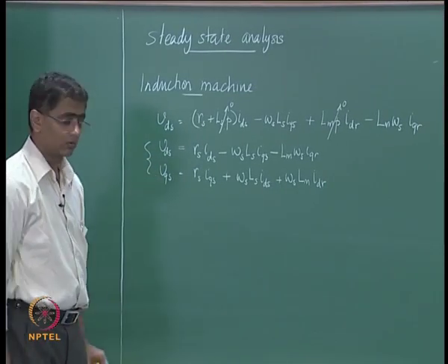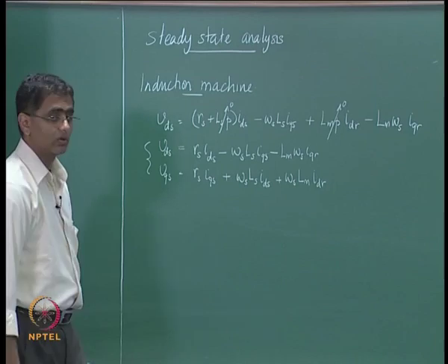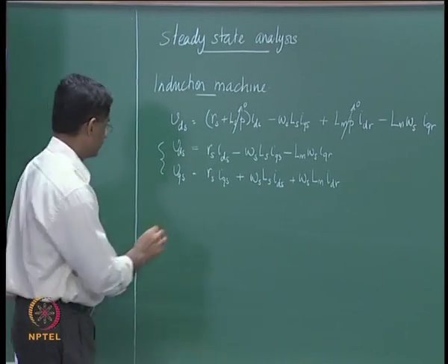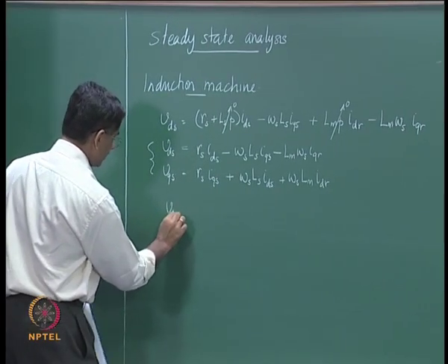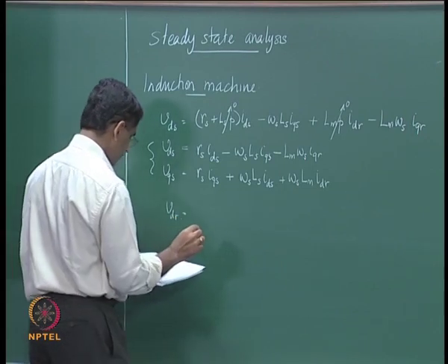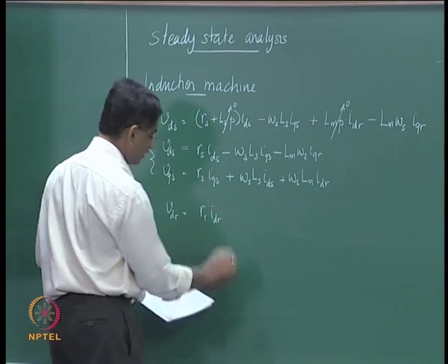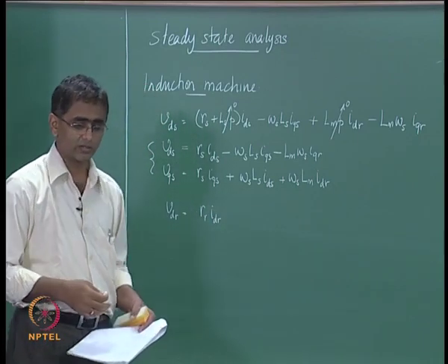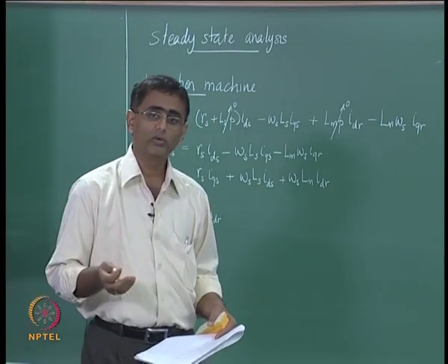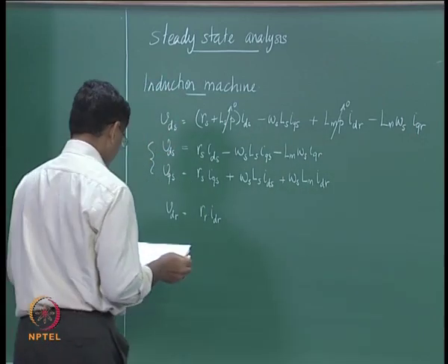for the stator voltages. Similarly, you will have two expressions for the rotor voltages, that is Vdr equals Rr into Idr. Again, d by dt terms can be neglected because we are in the synchronous reference frame.